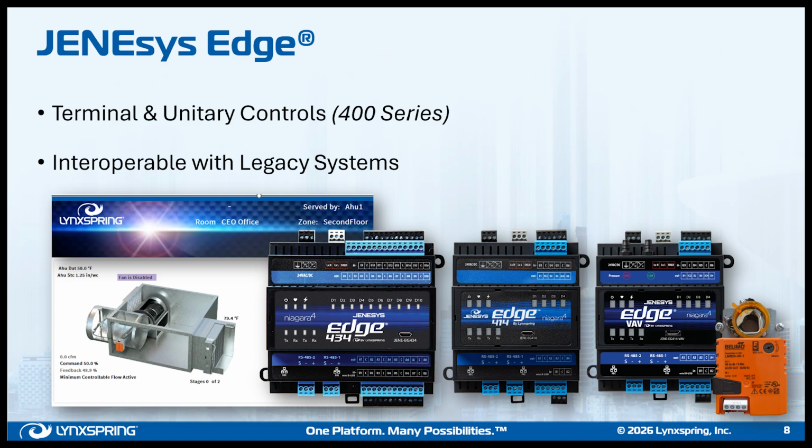When a controller goes down, you can pop in a Niagara device, communicating BACnet if you need to, or you can have a parallel IP network and run these things on a Fox network itself. There is an application specific VAV with about 28 different applications, including G36 included on that VAV.